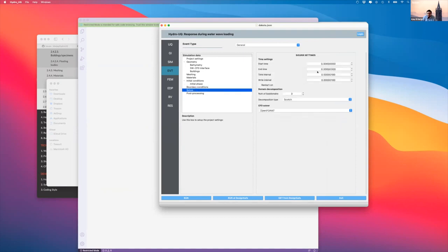So finally, the solver. I'll just run it for 3 or 5 time steps so that we are able to quickly see the results, hopefully before the end of the session. You can probably run it for much longer. One thing when you're running it is that your write interval would probably want to be much higher. I would put a write interval of 0.1 rather than this. But since we want to see some results here, I'm just going to keep the write interval and the time interval the same.